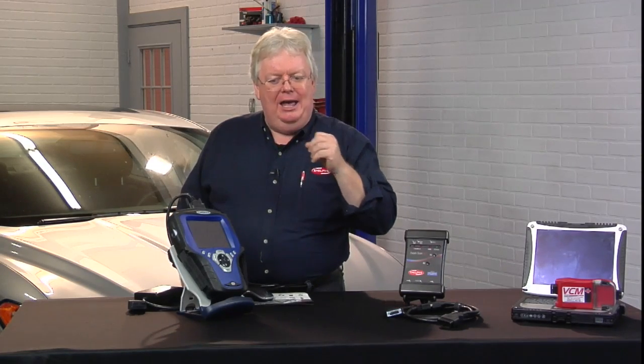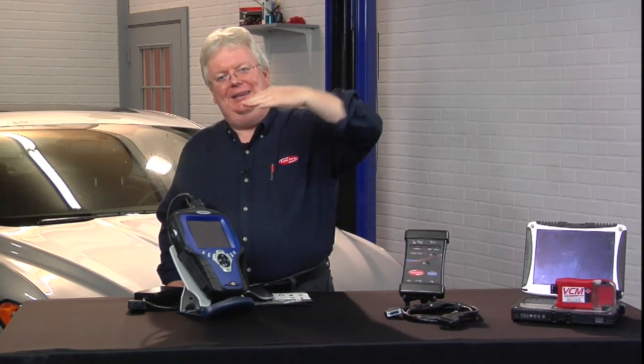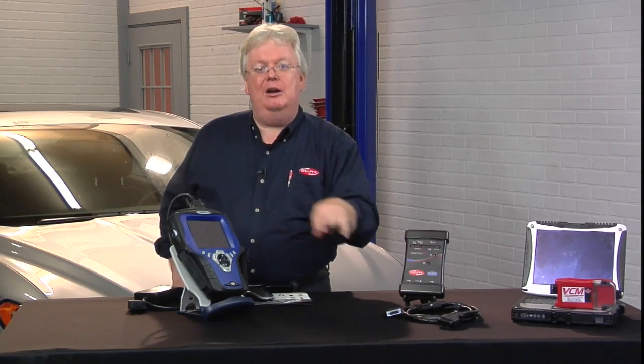Because there's nothing worse than going, well, let me see. I've got a drive cycle book that tells me how to do all the 8-9 minutes of whatever of all the different speeds and acceleration, deceleration, foot off the brake, foot on the brake, all this kind of stuff. But wouldn't it be nice if the monitor was a more simple set of criteria to enable it, to make it run, if we just knew that? So if you've got that on your scanner, use it. You'll really get a big kick out of it.